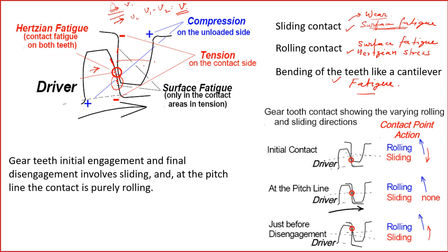So as it goes towards the pitch, there will be pure rolling, no sliding, and again going back, again there will be sliding. So rolling and sliding continues. Now another thing is, as the power is being transmitted, a huge amount of force is being applied. So when this driver applies force here, you will get compressive stress here and tensile stress here.